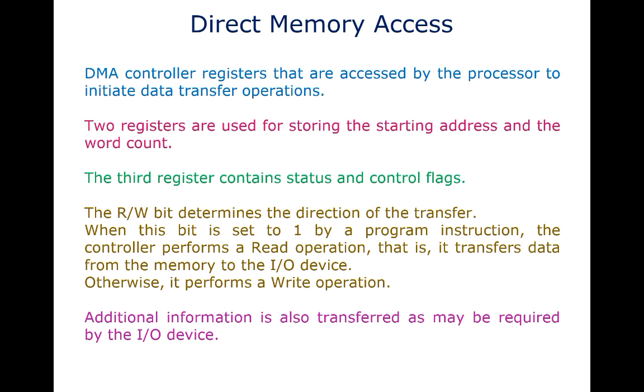So the next thing we need to consider over here is how this DMA transfer is going to happen. The processor normally provides three important pieces of information, such as the memory address, the number of words to be transferred, and in what direction the transfer goes. So these things are involved over there. Once this information is available, this DMA controller can begin the operation independently.